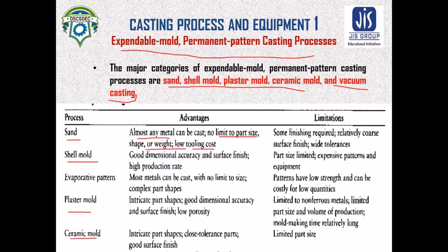But after the casting some finishing or finish machining is required. The surface finish is not so good, and it has wide tolerance. That means the dimensional accuracy does not match the design in case of sand casting, so further machining is needed.